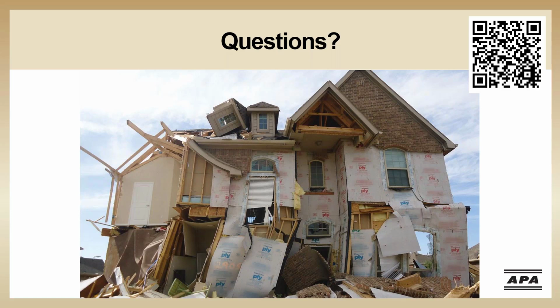So in general, balloon framed walls are going to need to follow the same rules as platform framing. That means they'll need to span from floor to roof, can't have any hinge connections because they need to be able to transfer that wind load from those studs to the roof and floor sheathing. Some of the details might look a little bit different between the different methods of framing, but overall the load path is generally the same.